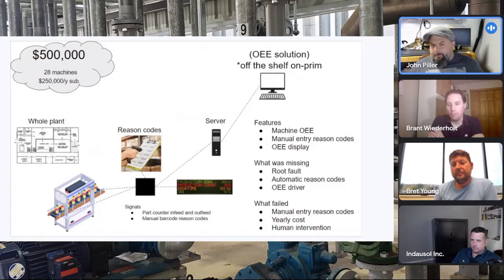It did not matter, interesting enough, if it was a very hot or a very cold environment. The problem, so now I gotta turn off my electrical and motors and 3-phase and flip on my process and circuit board level discussion of my degree. The problem was that there was a single UART on the board, and that single UART was managing data traffic for the Wi-Fi and data traffic for the serial USB port. And so we were over pegging that UART, and we were cooking the chip at 85 degrees C, no matter if it was cold or hot or anything.